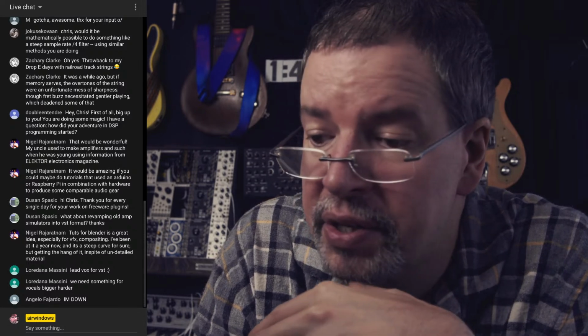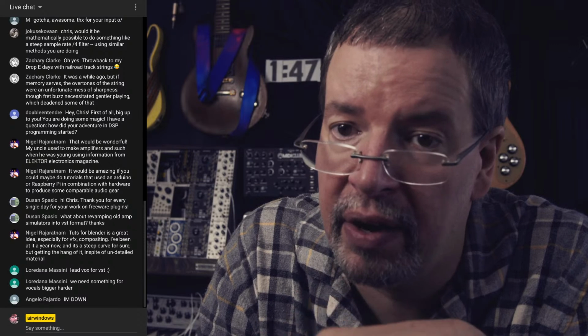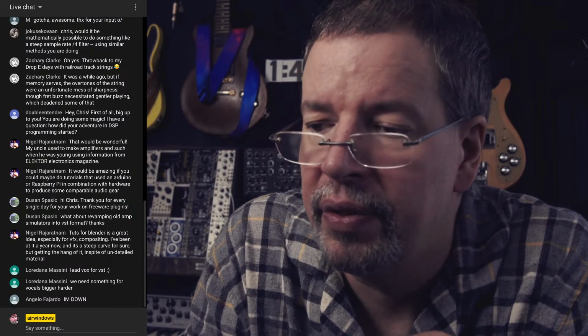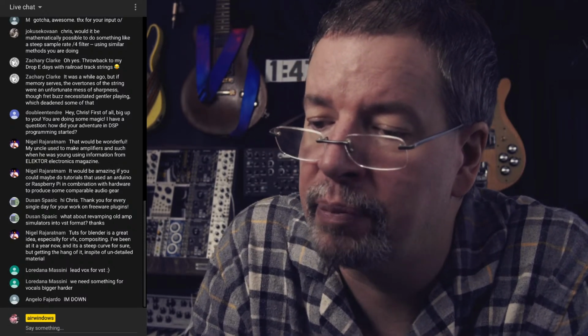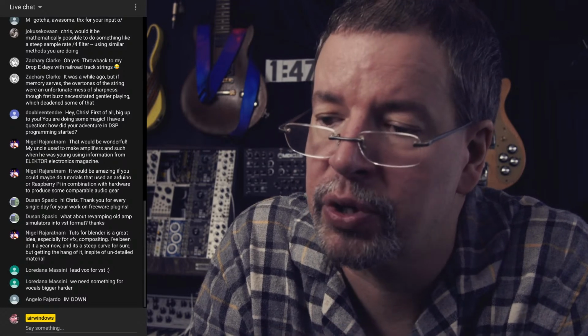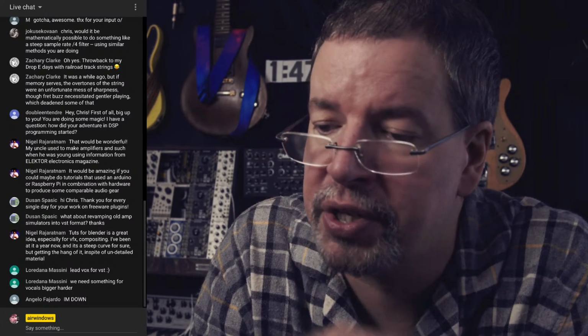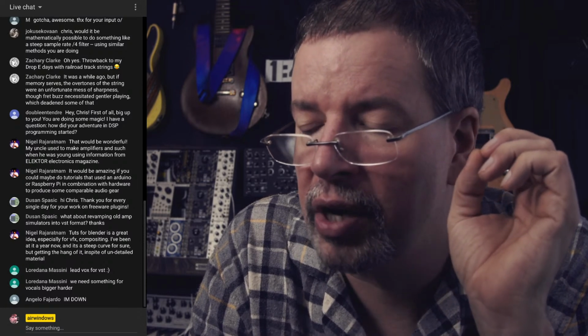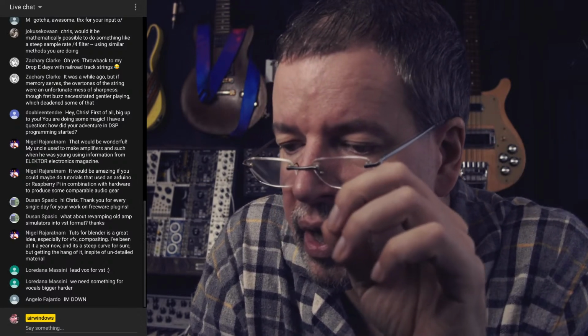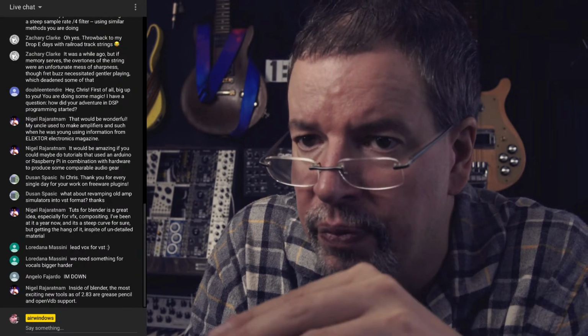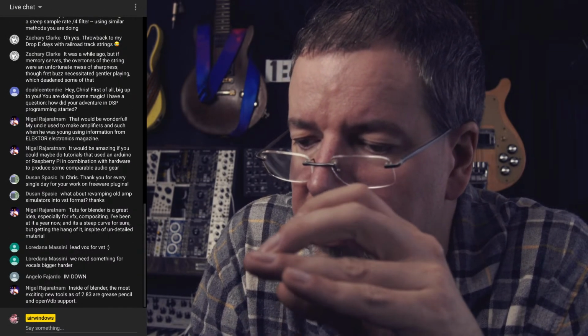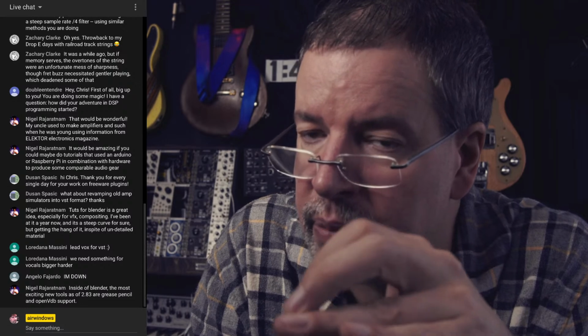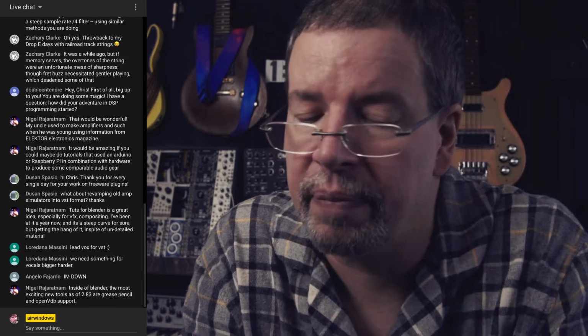And the deal is that it doesn't have to be part of the same machine. You could have an input jack that is the raw input of the gate, and the feedback goes through a resistor. So this jack, if I plug it to logic high voltage, everything is going to be ones going through. And if I ground it, everything's going to be zeros, so you can override it.